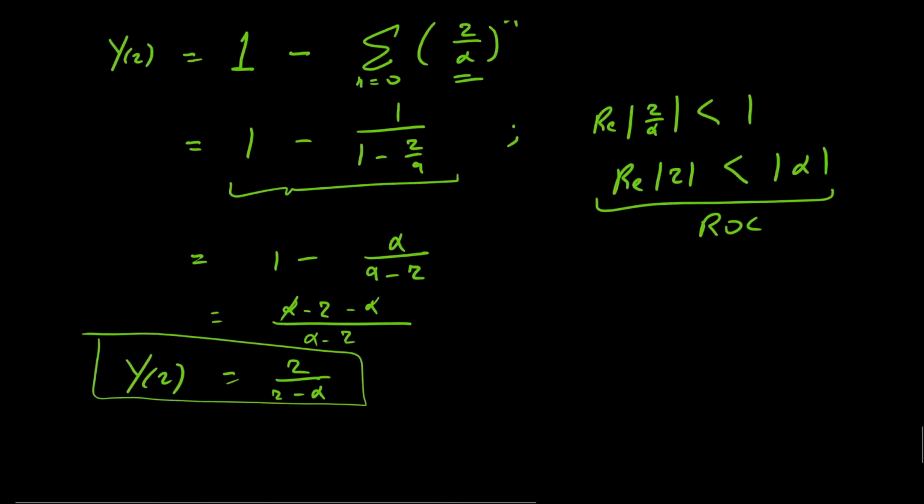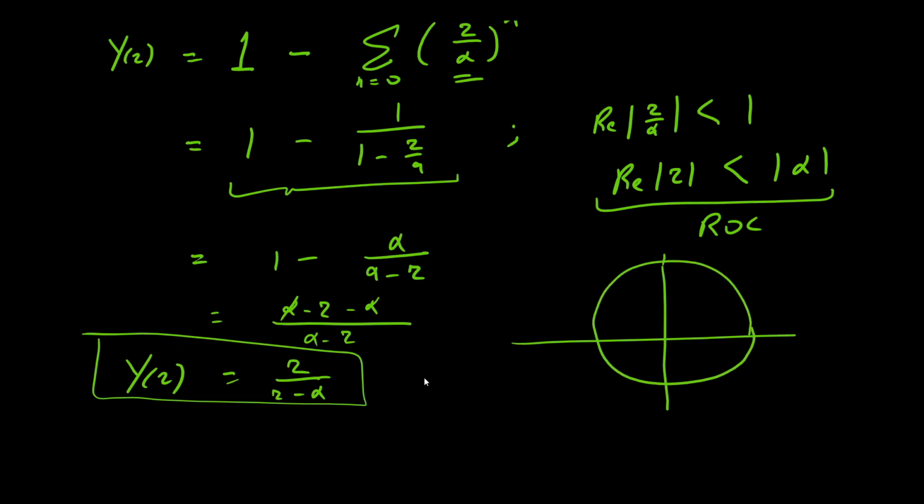So presently the region of convergence is that. Now again we have a unit circle, but the pole is at alpha. So say this is our alpha. So the ROC is inward. Previously it was outward, now it is inward. So this is when alpha is actually less than 1 but greater than minus 1. In the next discussion we would be talking about some of the properties of the region of convergence.